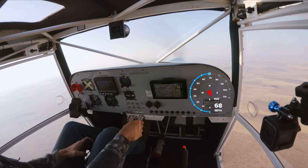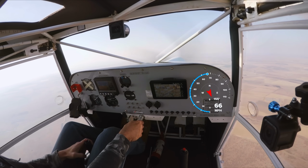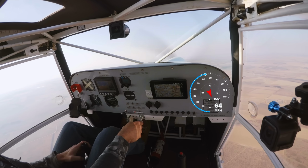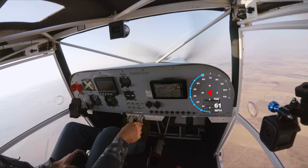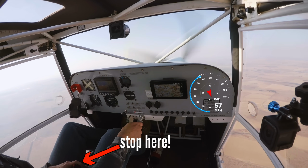Now try a stall yourself. Set up for a stall as usual, but instead of pulling the yoke all the way back, stop at about 75% backwards travel. Don't pull back any more than that. Now try to make the plane stall. It won't. It can't because you deliberately kept the angle of attack below critical with the yoke.